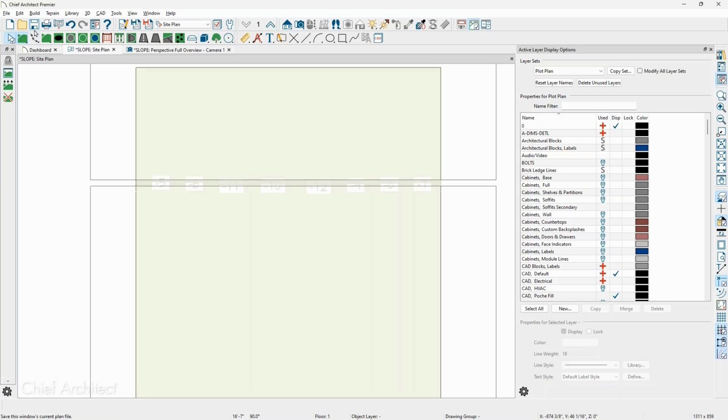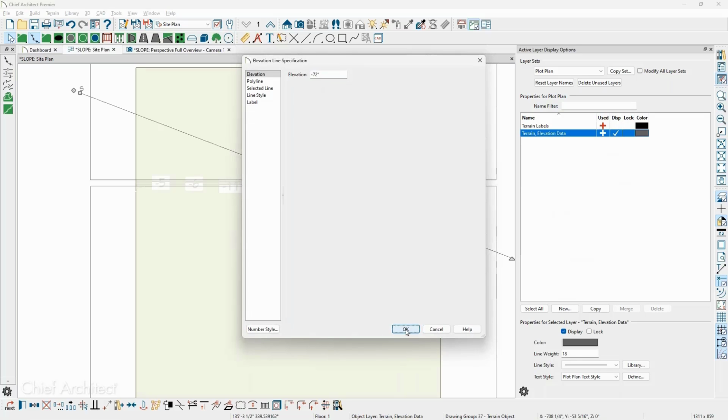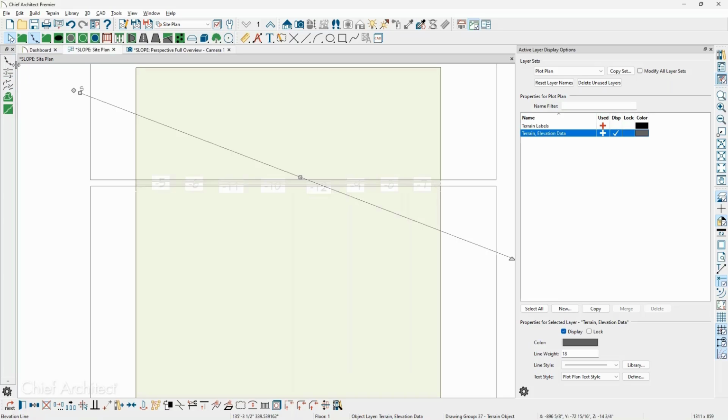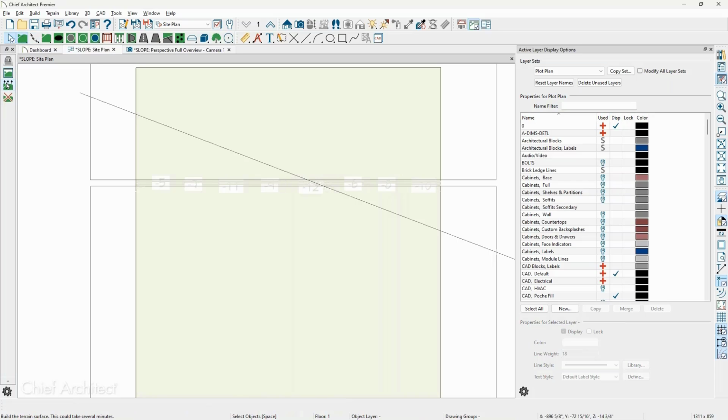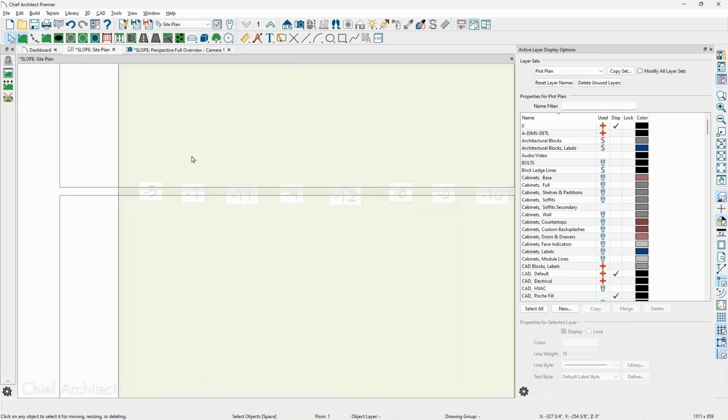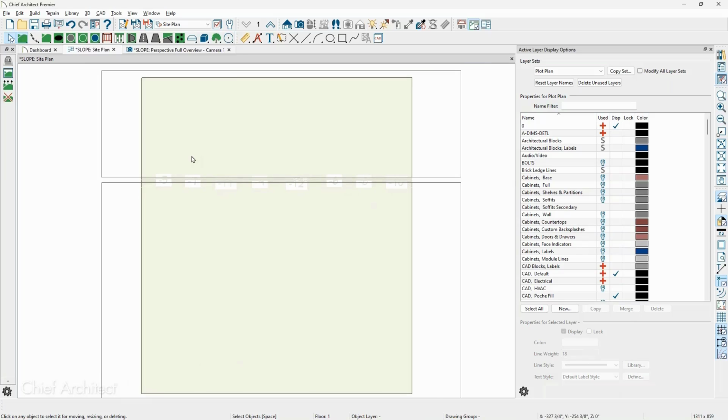or you draw an elevation line that may overlap, if I take an elevation line and I just drag this all the way through here and I set this to, let's say, minus 6 feet, and we regenerate the terrain, I'm not sure what's going to happen because this is competing. And sometimes if you have retaining walls that cross, let's generate that terrain and see what happens. It didn't actually have much of an impact. But when you have retaining walls and you have other data that overlaps in any way, you can get some pretty crazy results. So I usually zoom in and take a look at where these things may overlap to try to avoid creating those bubbles, or those fins, or those shark teeth around your terrain.